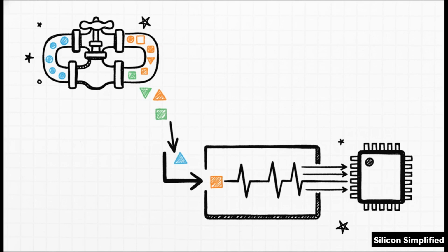Let's look at the active side first. The UVM sequencer acts kind of like a valve or a traffic cop. It manages the execution and arbitration of high-level transaction items, stuff like read packet or write data. It hands these abstract items one by one to the UVM driver. Now, the driver is literally where the rubber meets the road. It translates those abstract transactions into the actual binary ones and zeros wiggling the hardware pins on the clock edges.